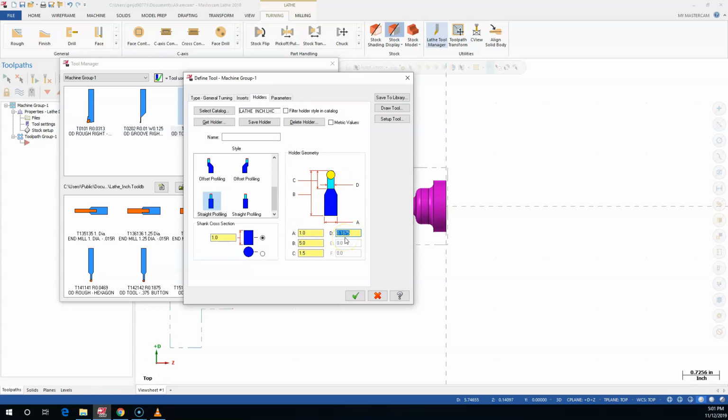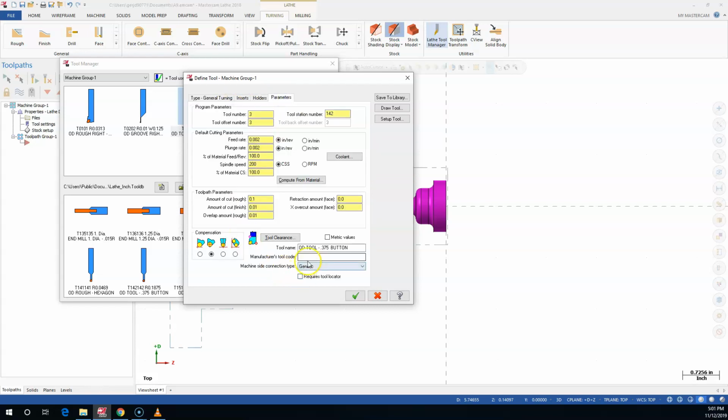Okay, so it shrank to 3/16 as well, so that should be okay. And if it doesn't bark at me about it, then we'll call it good. And somewhere I saw where I probably don't want to keep calling that a 3/8 and program it for a 3/16. So I'm just going to round to 0.19. All right, so tool number 3 is fine.